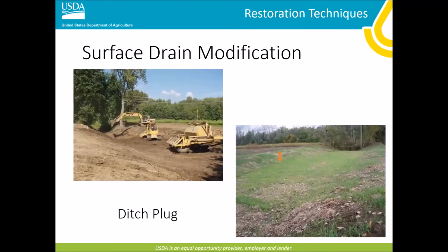Next slide. So that was about subsurface. Now we're going to be looking at surface modification. So we have our elusive ditch that usually goes through a lot of our project sites. A drainage ditch or open channel really needs to be modified if it's possible. There are easements or local regulations. I think the state of Indiana has a law prohibiting obstructions of mutual drains, so drains that serve a purpose for more than just one landowner. So be very careful when you are doing these ditch modification projects that you're not going to be backing it up onto a neighbor or preventing the drainage from that neighbor.